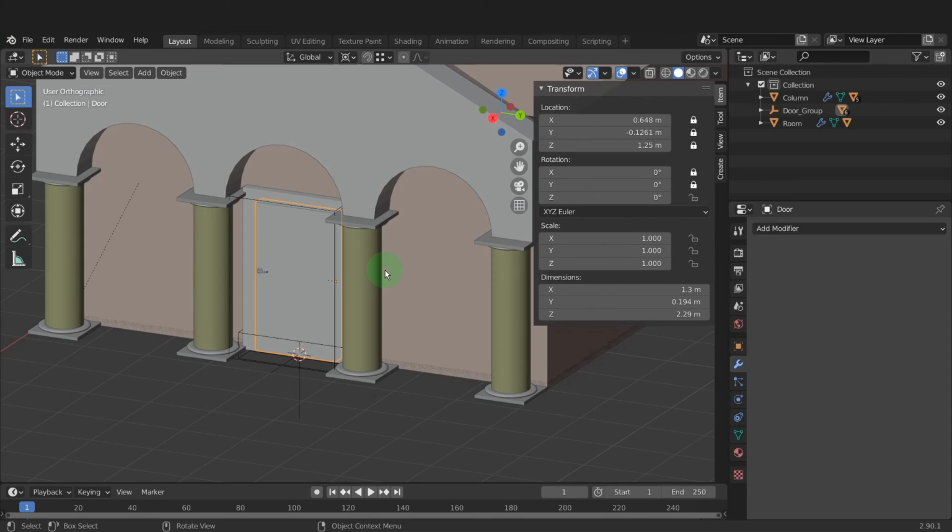The next piece of the door is the control hole object. This is the first cube-shaped object displayed as wire. This is used to subtract the cube shape from whatever the door gets inserted into. This results in an opening being created, and we can take a look at that in a moment. This second cube shape displayed as wire is used to subtract the baseboard if the wall has one enabled.